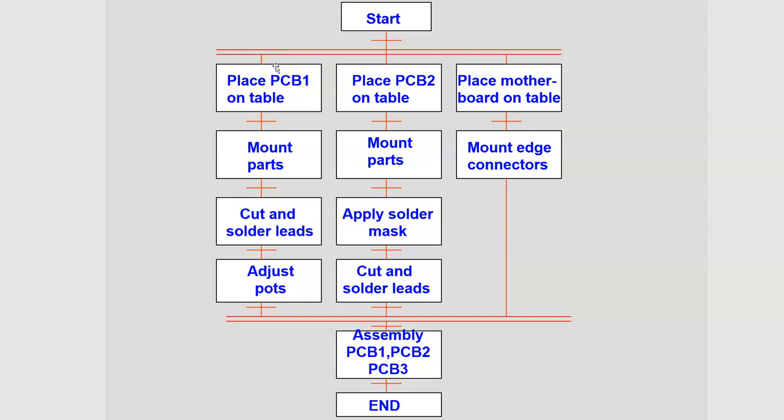if you put the one most likely to be false, if all of these are true, it's looking for the one that's false to go through and to become true. So you would have the one most likely to be false. I would put that further to the left. You don't have to do it that way, but we're talking if you have a really long program using a lot of these structures, then you can actually gain a little bit of scan time by just doing these little tricks. But it'll work either way. So make sure you understand the logic of this.